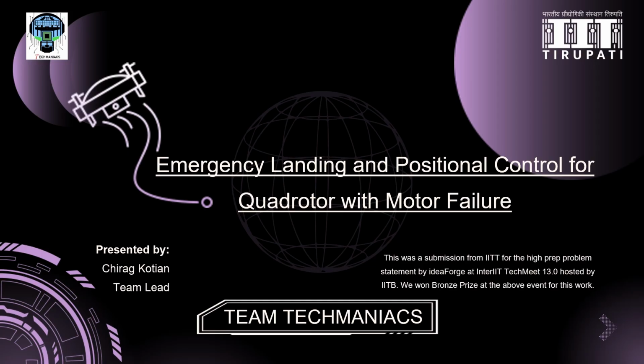In practical terms, a quadrotor normally has 6 degrees of freedom: 3 translational (up down, forward back, left right) and 3 rotational (roll, pitch, yaw). But with only 4 motors, it's already an underactuated system. Losing one motor makes it even harder to control.